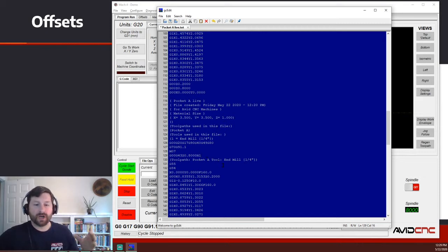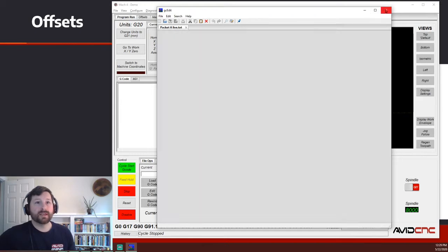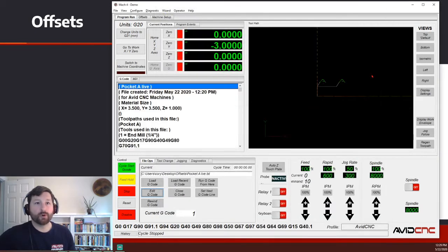And so now I've copied my toolpath, I've deleted one line of code, and I've added a G54 and a G55 code. And so I'm going to save this now. And now when we go ahead and open up Mock, you'll see we have a preview of two A's side by side. And so let's do this scaling.